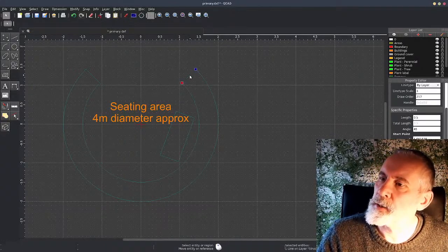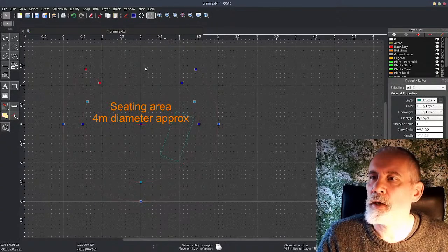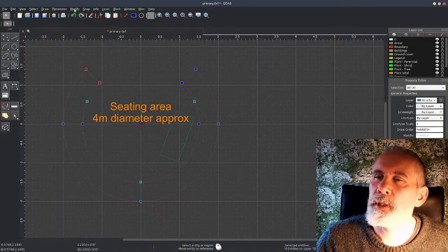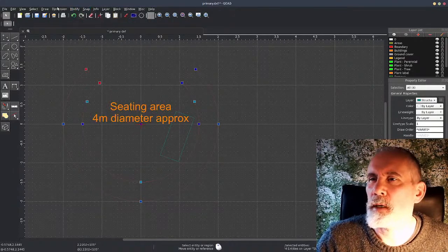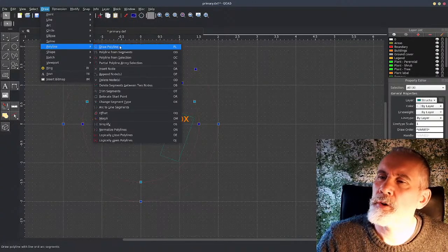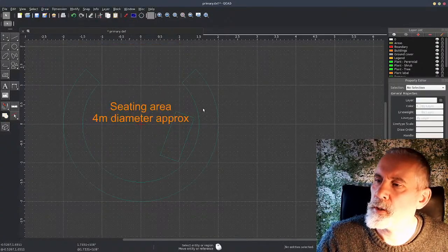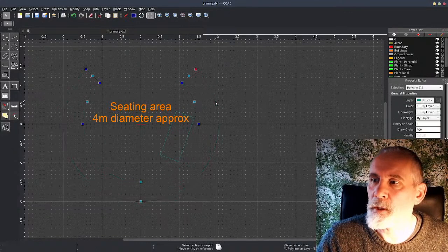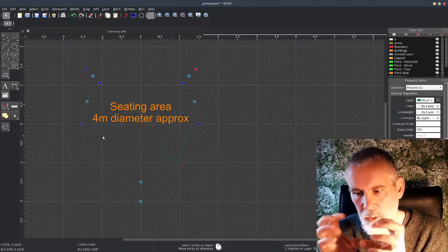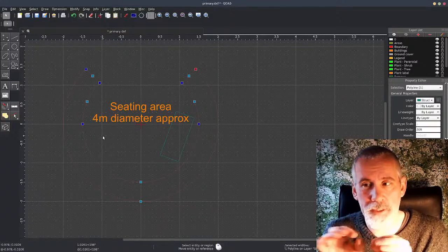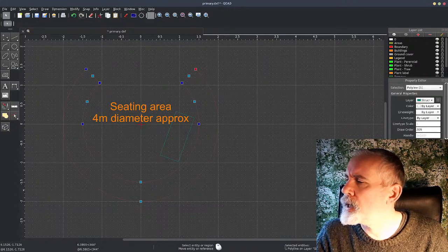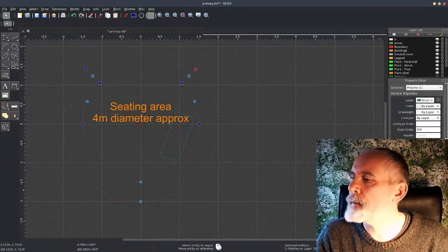So creating a polyline, you see here in the properties, these are individual lines. But if I double click, it will select all of them together. That tells me that they're all joined up. It can be a bit tricky doing this, but you know how. So draw polyline, create polyline from selection, and now look at this. I click that, it's acting as one item, as one enclosed shape, and this is the super cool bit. I can see from that shape that its total area is 4 square meters.